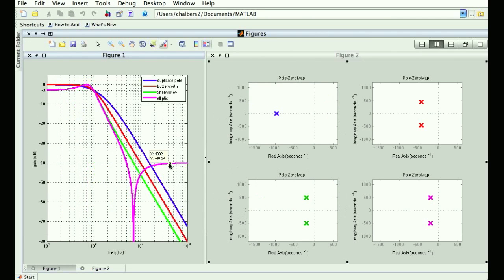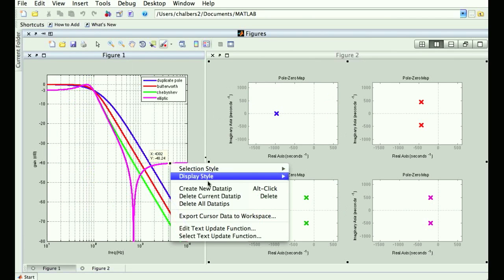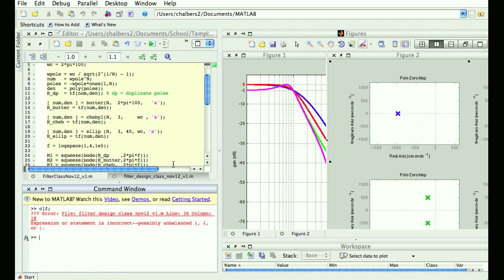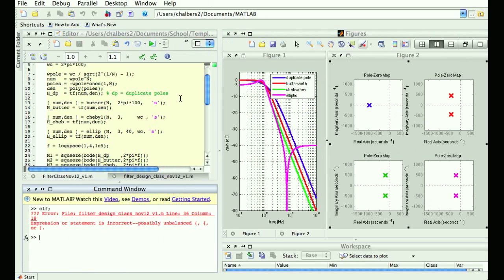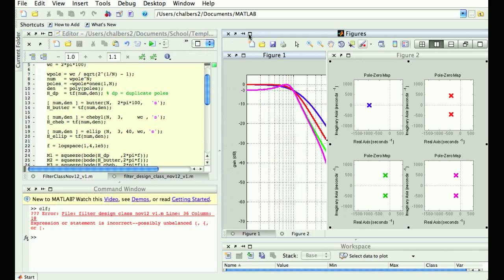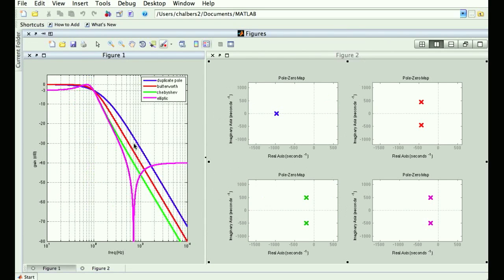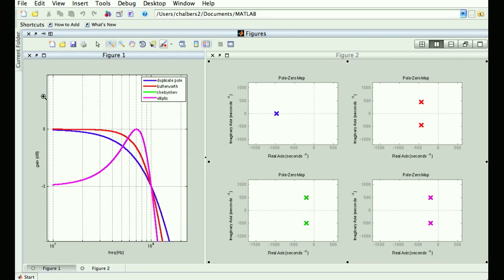But now let's compare the red one and the green one. Which is a better filter? Depends. The green cuts off better, and if you're really looking for the frequency at the cutoff frequency, it will pass that perfectly fine. If you want to pass the band in front of it, it's going to be a little bit less than red though.